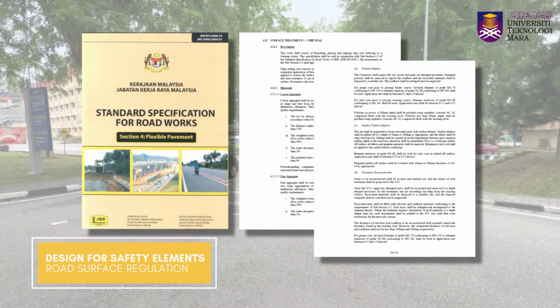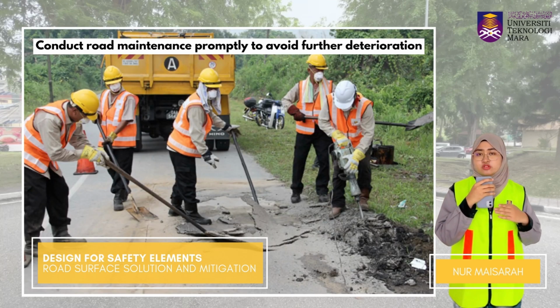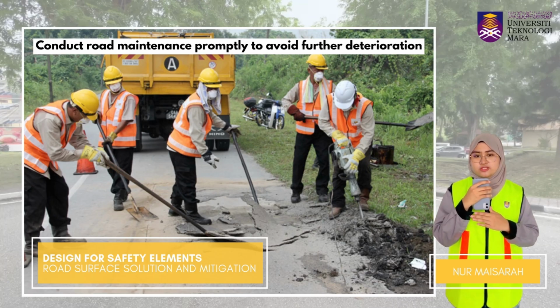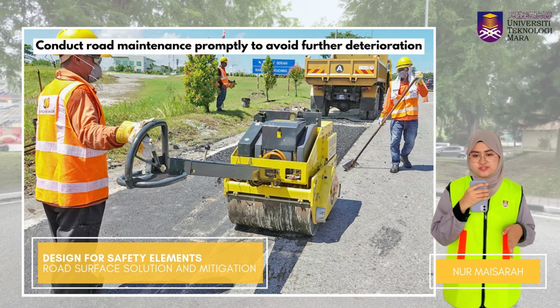It explains about the materials specifications such as bitumen, aggregates, and modification works, and also the maintenance work of the road surfaces. Now, for the solutions and mitigations of these road surface problems, the first one is road maintenance. The road damages and defects need to be repaired promptly in order to prevent further deterioration, for which we could use sealing or patching on the road surfaces.